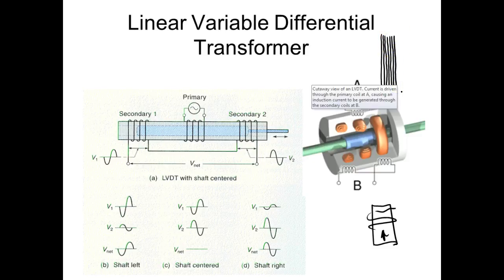Well, it's not really a dielectric. All it is, is that we're insulating these conductors, these metals, from each other. So all the little currents that are induced inside these don't add together. By the way, these little currents that we don't want are called eddy currents. So the eddy currents induced into one do not add with the other.